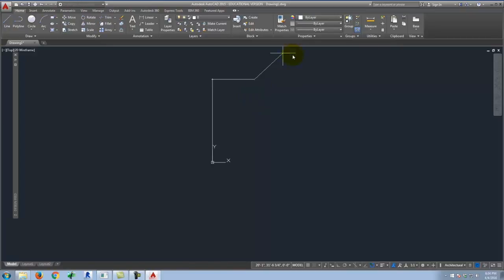And so instead of what's called an absolute coordinate, which means the 0, 0 is at the origin of x, y, we can use something called a relative coordinate. And a relative coordinate resets x and y to start from the last point you clicked. So in this case, it would start from right here, and I can now reorient from this location.